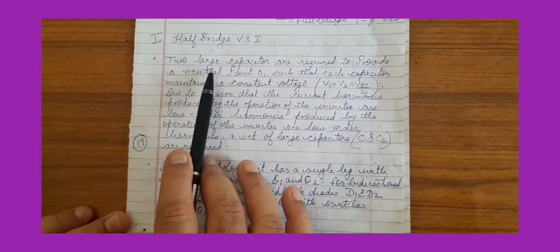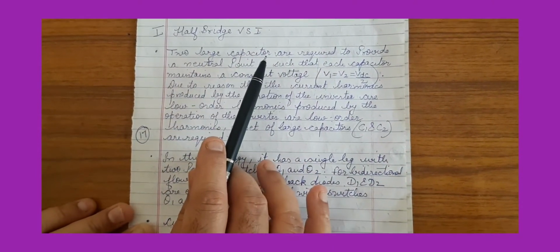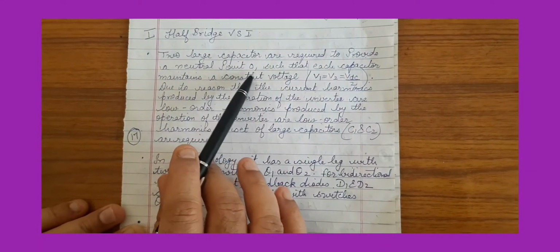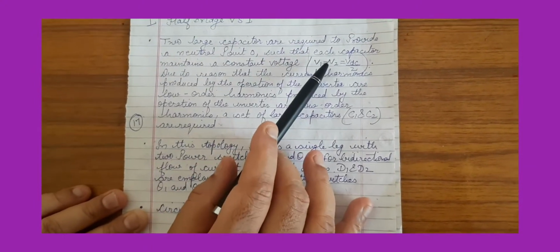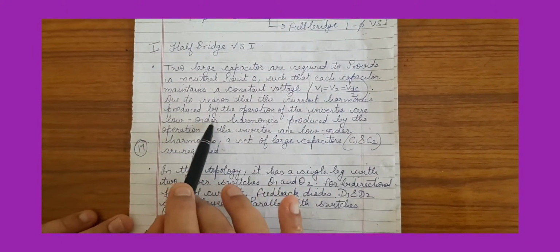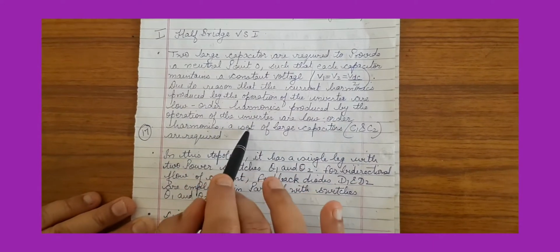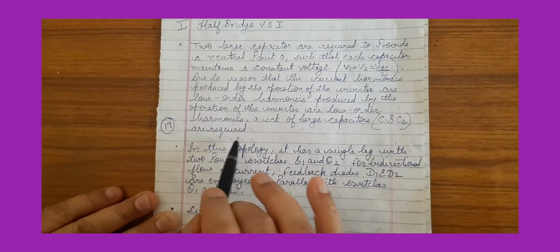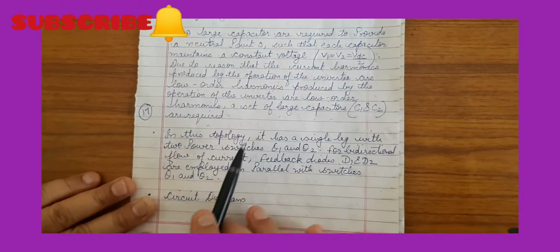The circuit diagram of the half bridge voltage source inverter consists of capacitors which are required to provide a neutral point O, such that each capacitor will maintain a constant voltage, that is V1, V2 equal to VDC upon 2. Because the current harmonics produced by the operation of the inverter are low order harmonics, a set of large capacitors is required. This is the reason why we require the large capacitors.